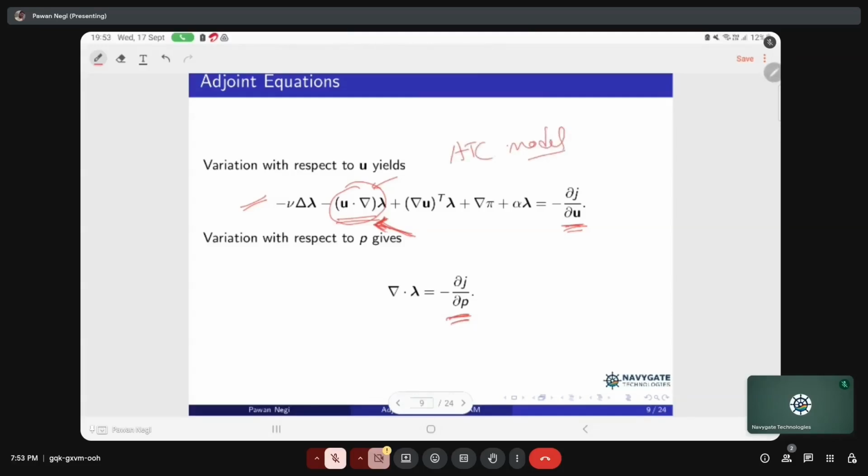And while writing the scheme also, we have to write the divergence term for these as negative of rho times u instead of rho times u or rho times some other parameter, like in primal. These are some of the differences that you will notice in the OpenFOAM implementation. Boundary conditions are also a little bit different, which are defined in the adjoint source code that we'll go through when we set up the shape optimization or topology optimization using the adjoint solver that is present in OpenFOAM.